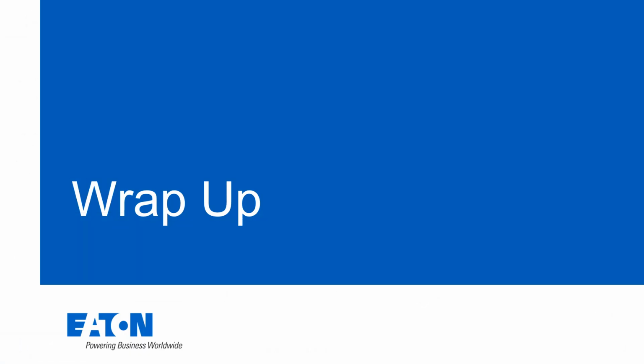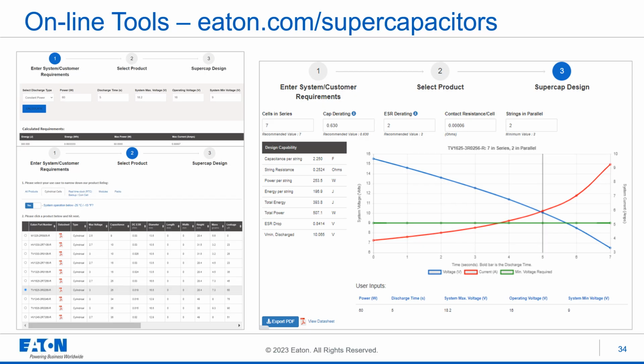To wrap up, we looked at how to make calculations to come up with a supercapacitor design, but instead of doing manual calculations, you can go to the Eaton website to find a web-based version of the spreadsheet I showed earlier. Go to eaton.com/supercapacitors, scroll to the bottom to find the supercapacitor calculator. Input your design requirements in step 1, simply the parameters that I showed earlier in the calculation for system voltage, maximum and minimum operating voltage, power or current, and time of discharge.